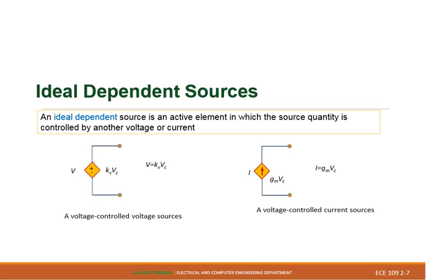In this case, when you look at this one here, this is a voltage source, we know it. And we see it is controlled by another voltage here, VC. The KV here is basically a constant coefficient. That's why we call this one a voltage controlled voltage source. So the voltage right there, VAB, will be equal to KV times VC.